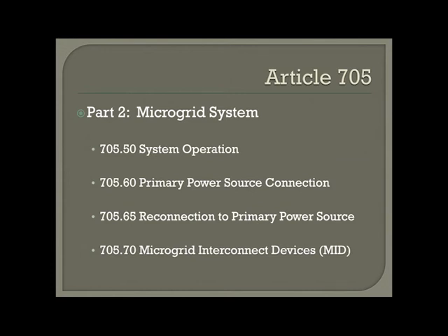Of course, it's not their meter socket, it's their meter. I suggest you use lugs in there, is your best alternative for tapping onto the supply side. If you want to use Article 705, very good idea, but you can do what you want. But my biggest beef is staying out of the meter socket except with the load side or the line side of your PV system.